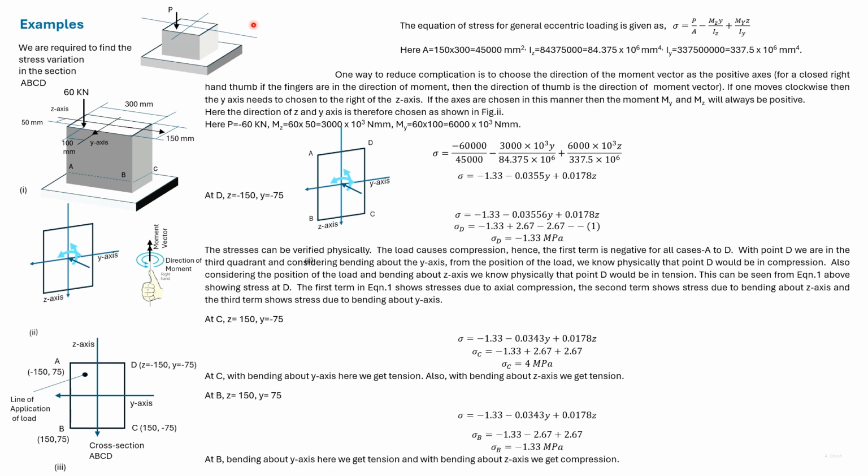We initially do not assign the axes. The distances of the load P from the axes of symmetry are given, and we can find the centroidal load and the moment that will act on the section. We'll use this formula, and as such, we'll consider the z-axis to be 90 degrees counterclockwise to the y-axis.